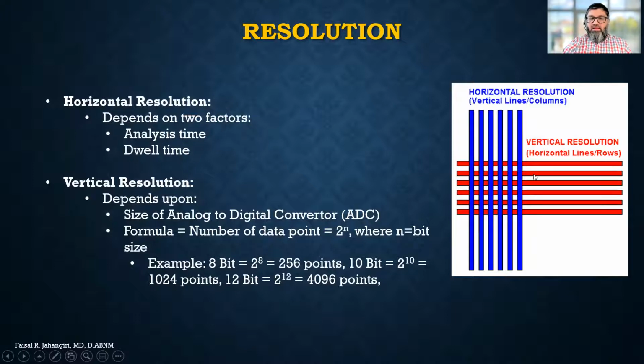It depends on the analysis time and the dwell time. So the horizontal resolution depends on the sweep, the time of recording or analysis time, or the time between the samples. If you have less time, the resolution will be better. If the time between two data points is longer, then the resolution will be poor because the curve will not pick up the signal as clearly.